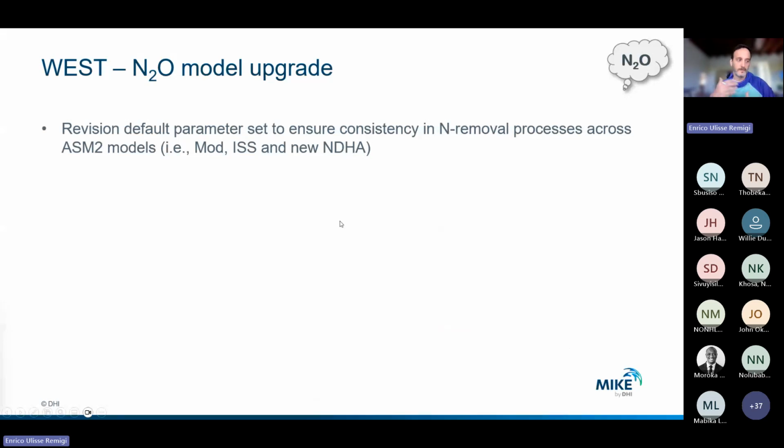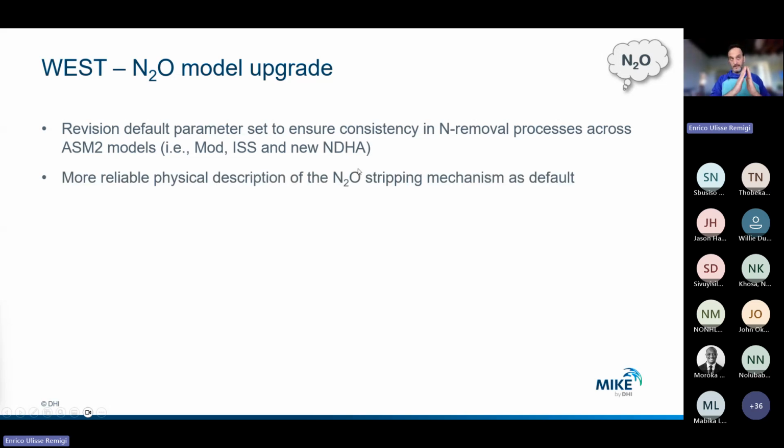I mentioned that we are maintaining and improving, in particular, the latest models that we introduced with recent versions, and this is the case for the N2O model. In 2025, we've revised the default set of parameters, so that the different ASM2 flavors that you find in WEST, what is called ASM2D mod, ISS, now NDHA, are all consistent in the common elements.